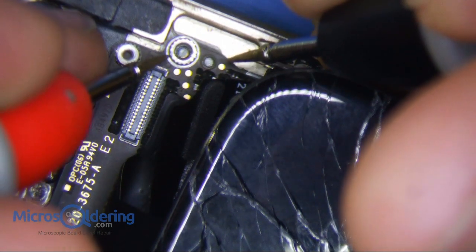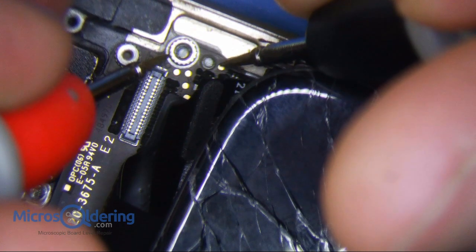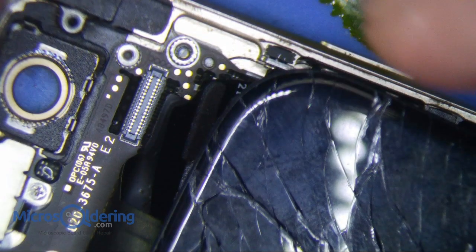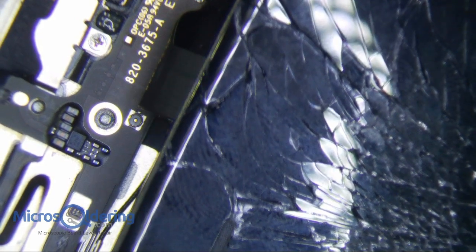Okay, now I'm going to test the other anode connection. So this one's giving me 3.8 volts, which is essentially telling me that the boosted voltage is not getting through to this side for some reason. Right. Which is why I have a dark screen at the top right of the screen. Okay, so that's kind of how you determine it.